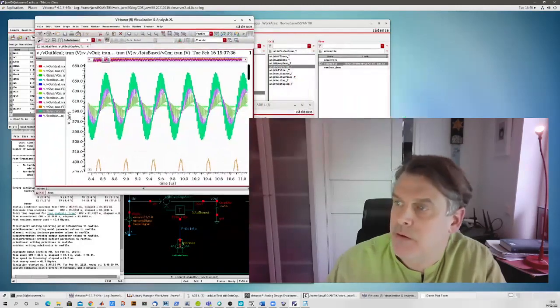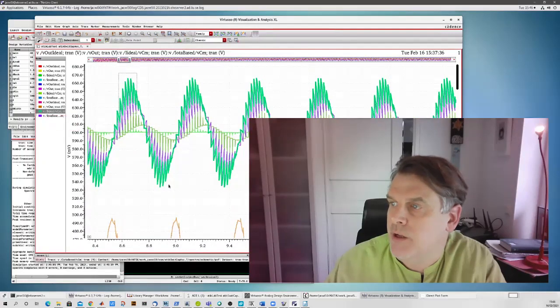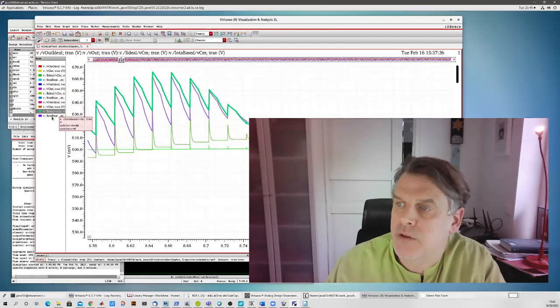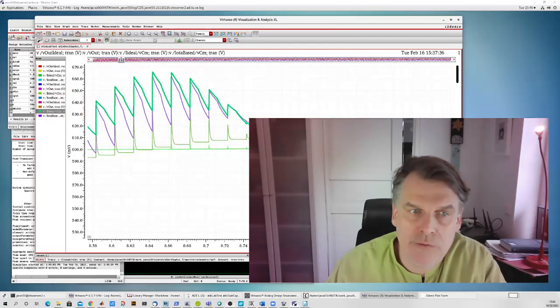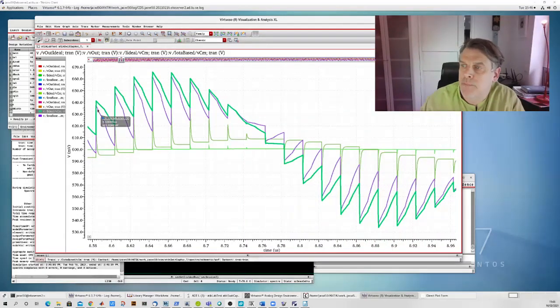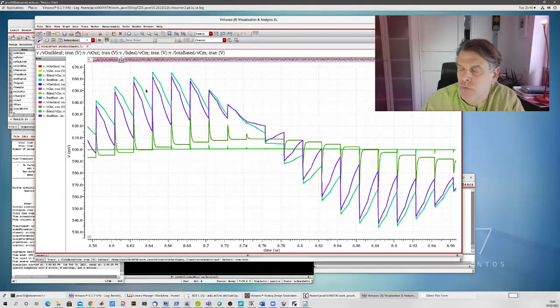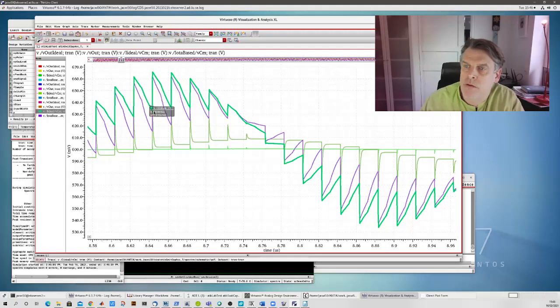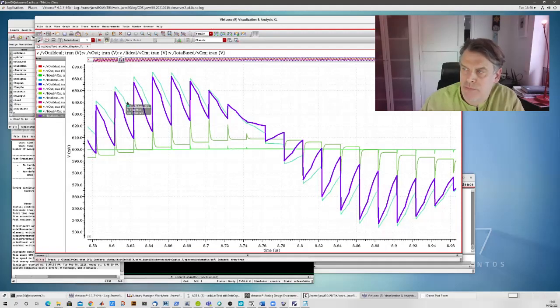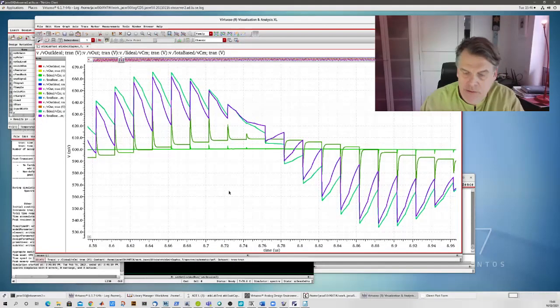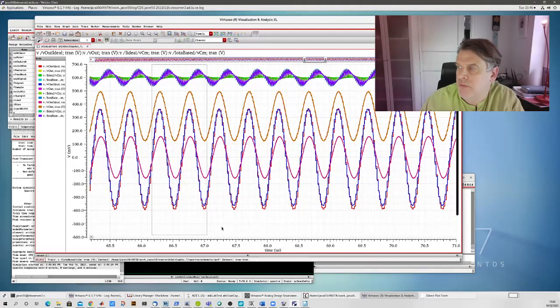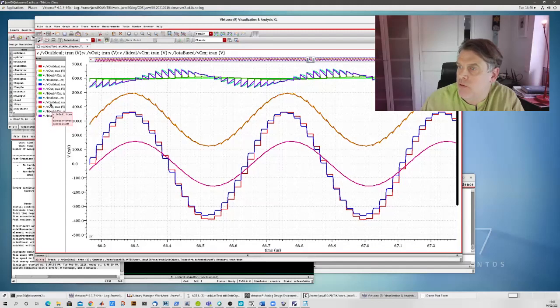Okay, so now the pole frequency was much lower, and now we have an ideal voltage, the green one, and we see the green one with poor gain and poor bandwidth. Sorry, I'll remove my head here. So I reduced both the gain and the bandwidth of my system. And now we see that, funnily enough, the other green one for the ideal one more or less looks like the op-amp one. They are almost identical to some extent. So it seems like we mimic our transistor implementation quite well with that assumption. Still, it looks a little bit better on the output than the op-amp does.